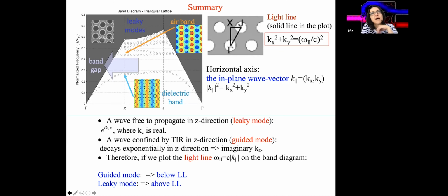I'll explain in a moment what that means and how we define that symmetry for photonic crystals. But what that also means is that you have to be very careful how you launch modes into your structure, because if you want to benefit from the photonic band gap, it would work only for a specific polarization of the excitation, because the other polarization would have no band gap. It is possible to control that. You can control it if you do passive excitation of the structure by lining up the input field polarization from your laser relative to the modes.